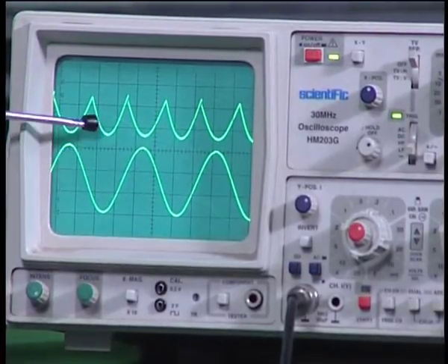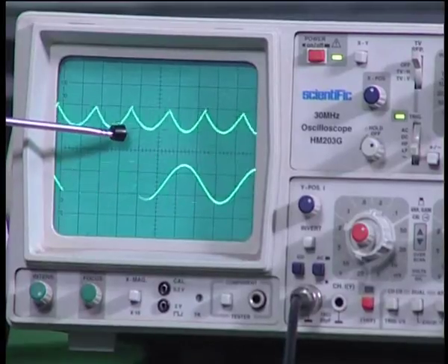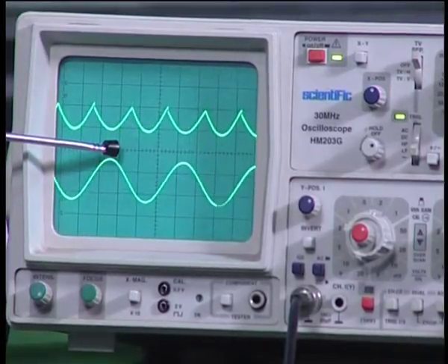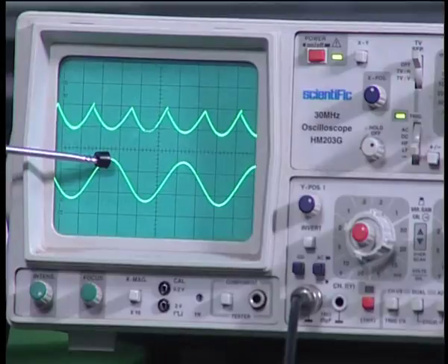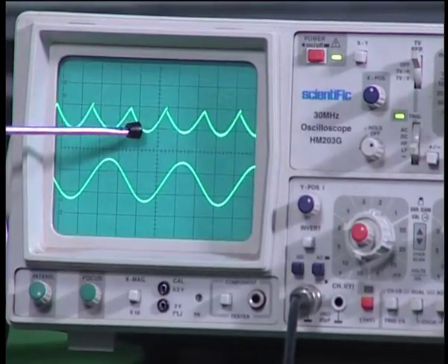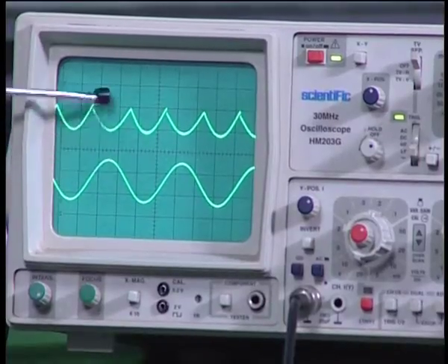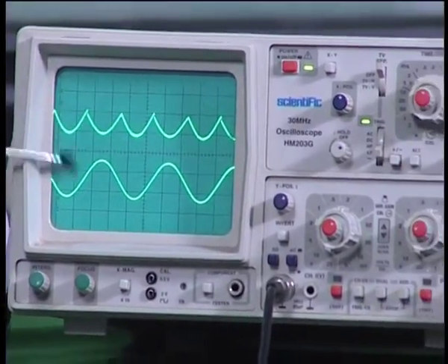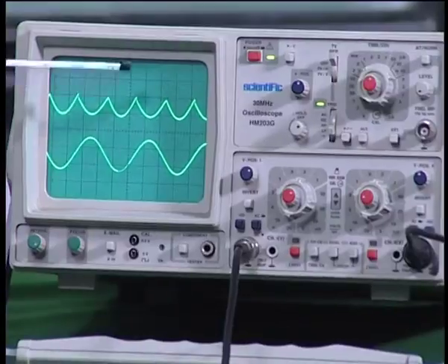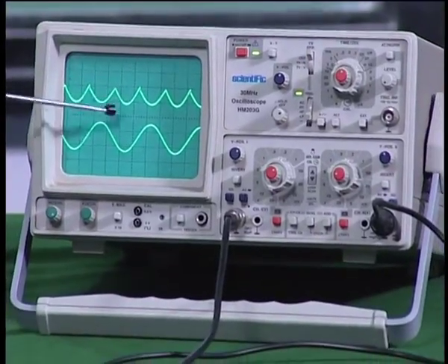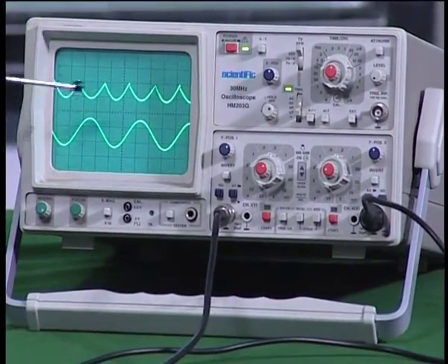If I vary the amplitude, as you can see on the oscilloscope, the output also changes here, and if you really measure the voltage, it is again around 0.2 or 0.4 volts, as you can see on the dial, and therefore, it is for very low signals that you get a full wave rectified output, and therefore, this is a precision full wave rectifier circuit.